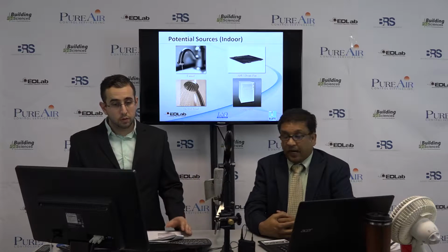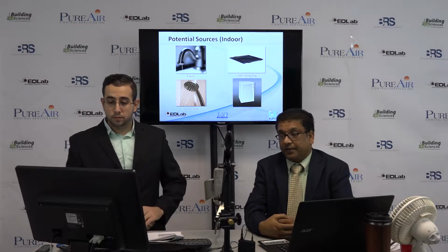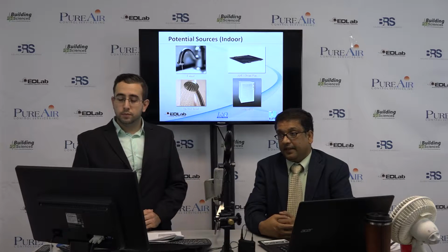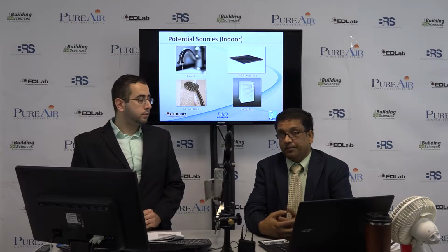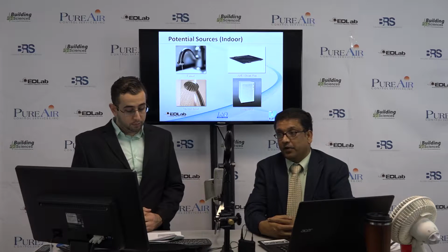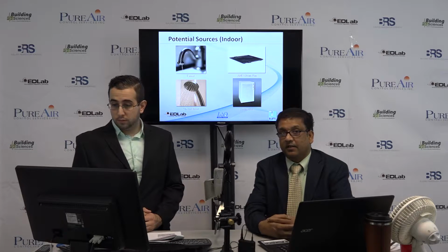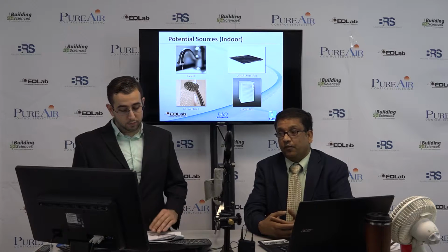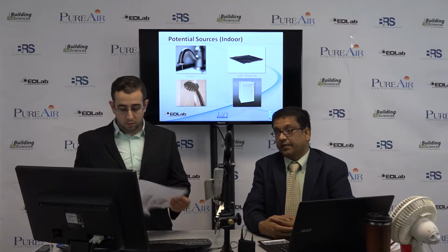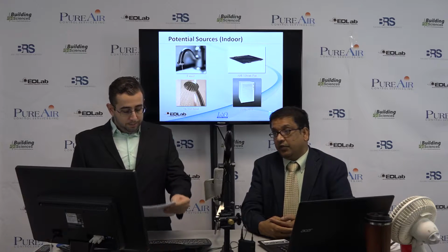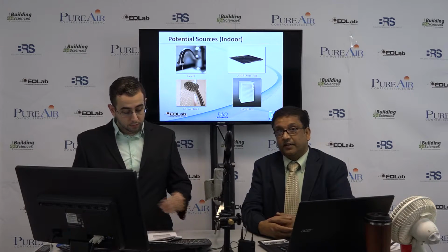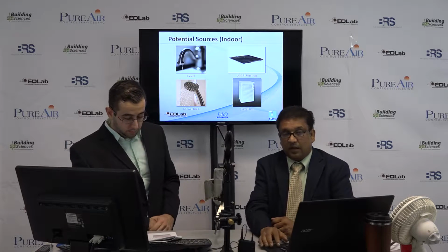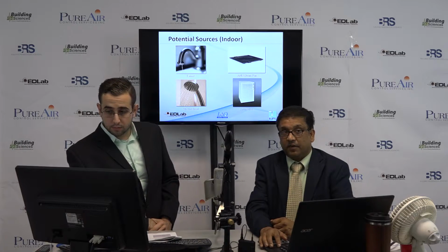Now, I wanted to give you a photographic idea of how you can narrow down the source. For example, the water faucet, which is very common in a dwelling place or in an industrial or residential setup, is one of the main places where biofilm can be formed, such as the shower head, AHU, drain pan, humidifier, etc. Those are really the places to look for, where Legionella can flourish.